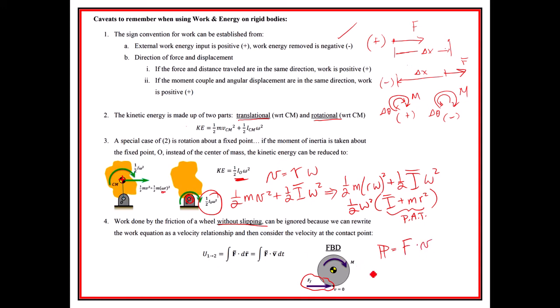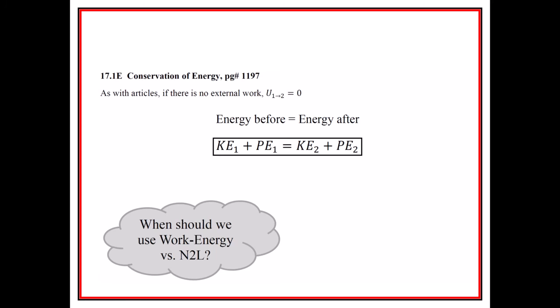And work can just be considered as the integration of power versus time, right? So we are left with this right here. If the velocity at the point of contact in the no-slip condition is 0, the power is 0, therefore the integration and the work or the energy loss due to friction is going to be 0. That's an important comment.